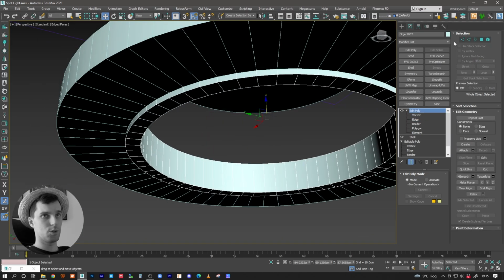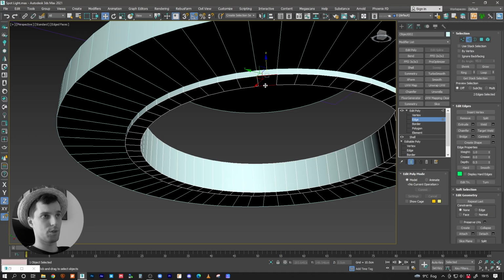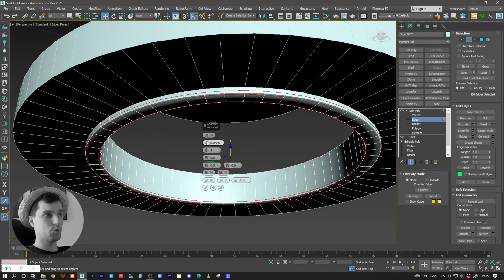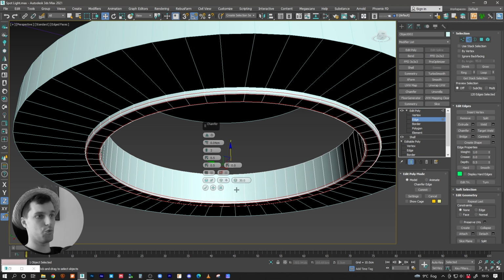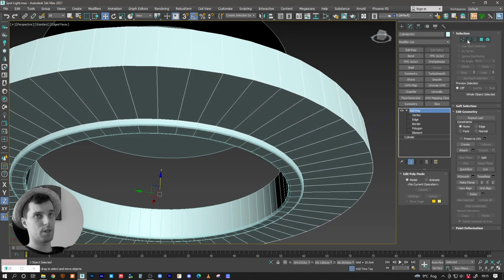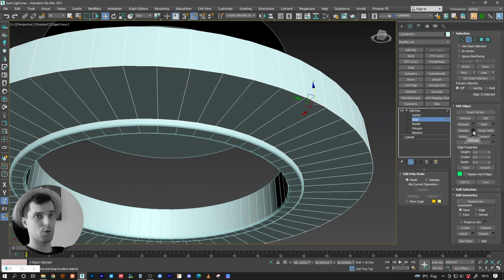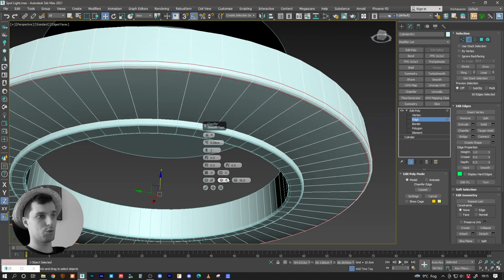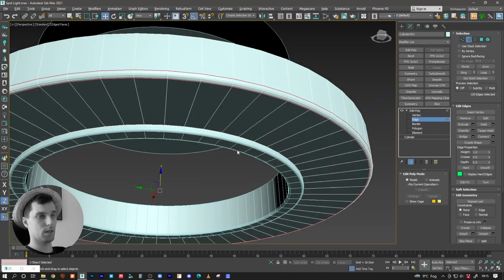And the next thing we can do is put some detail with chamfering. So select those two, and you can press loop, or you hold Ctrl and double click, and you can chamfer it, right? Don't do it too much. I would do 2 segments and do smooth chamfers only, right? So something like that, and do the same thing for the top bit here. So double click, chamfer, and do just a little bit, put 2 and like that, right?